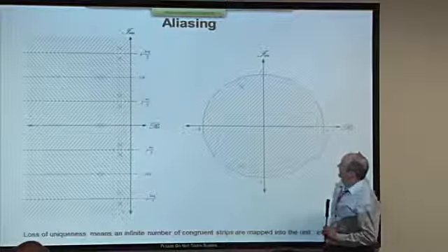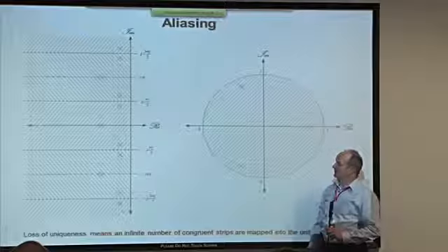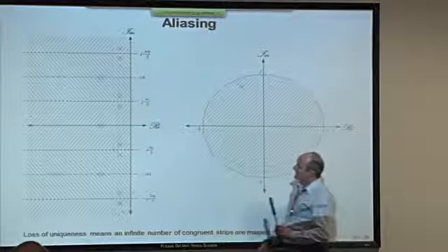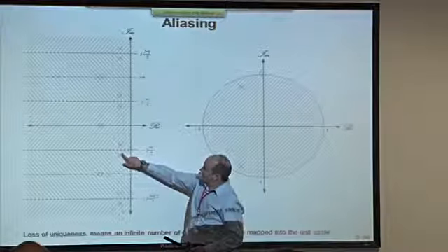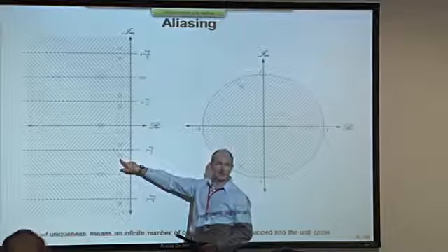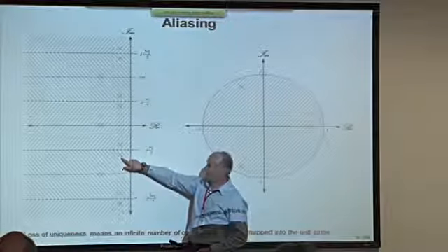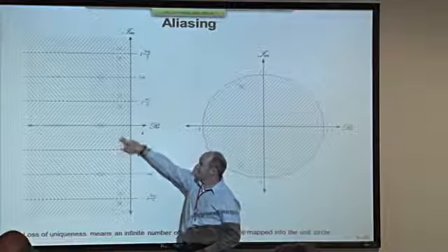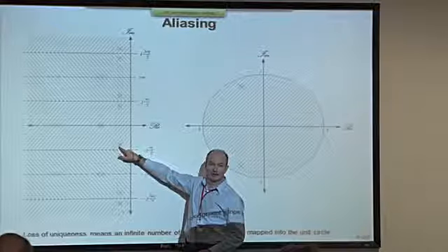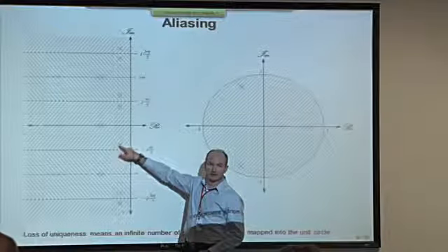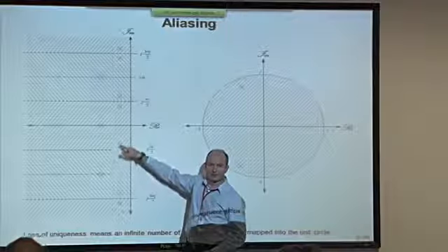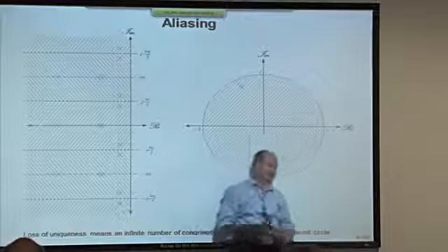Right? This is a concept called aliasing. And the reason it's called that is that imagine I'd placed a pole here, deliberately outside the primary strip. Well, aliasing would have reflected it down as if it had been placed there in the first place. I've created an alias. There's an ambiguity between these two frequencies.